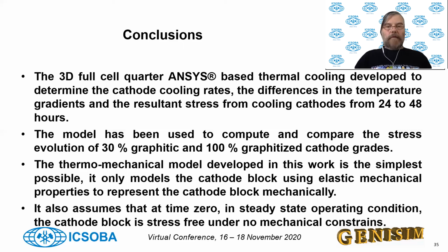We are assuming zero stress, zero strain at the operating temperature. So we are assuming that some creep has occurred in operation for long enough time so that the lining has settled down to some condition. And then when you start to cool down, some stress occurs due to the thermal gradient and to the boundary condition.